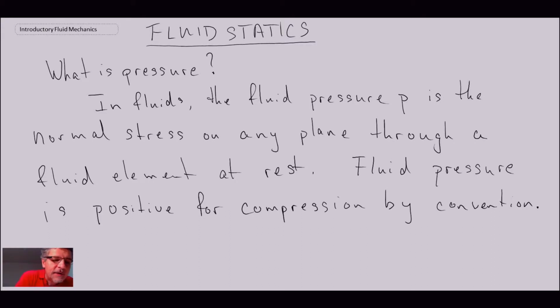So that there is a definition of pressure. We see that pressure is a normal stress that acts within a plane of a fluid, and in normal, that means that it's perpendicular to the plane, and it's for a fluid element at rest. And the other thing that we need to be aware of is that we will view it as being positive for compression. So what we're going to do, we're going to begin by considering a chunk of fluid, and we're going to take a look at what the pressure distribution is like within that. In order to do this, we're going to consider a static wedge of fluid.